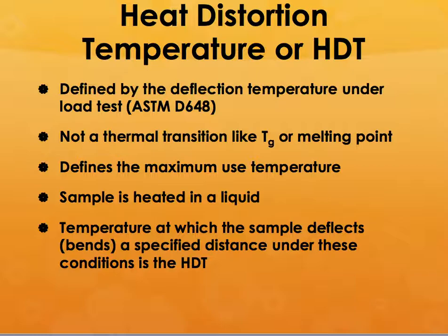It is not a thermal transition like glass transition or melting point, but it defines the maximum use temperature, which is a better definition of the maximum use temperature for a composite material. And the temperature at which it bends a specified distance under these conditions is the HDT.